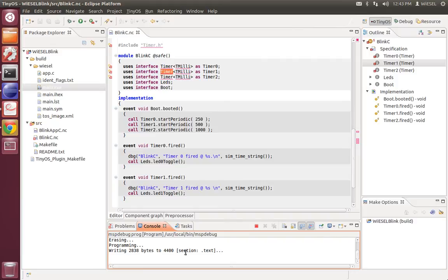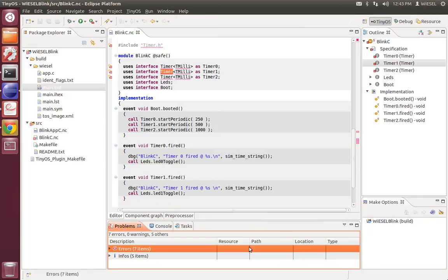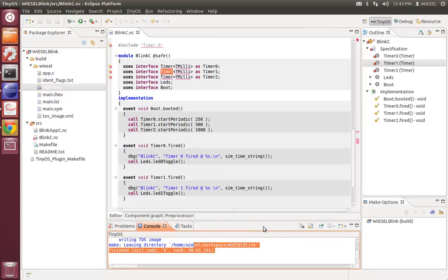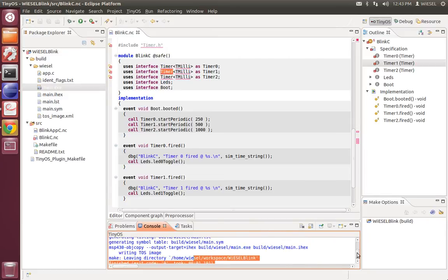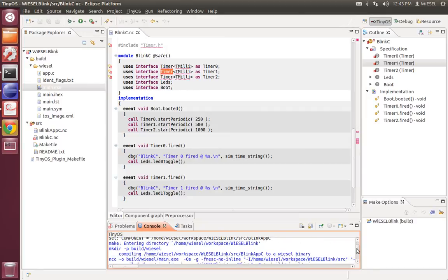It's programming the Flash code right now. And it will have 3 more small little sections that will be programmed, 2 bytes, 128, and that was it. And the board is blinking again. So that was basically programming the whole code now using a binary that was compiled. If we close this one here, so if you look at the compiled program again, you can see that GCC actually used the -g flag, so this now has debugging information.